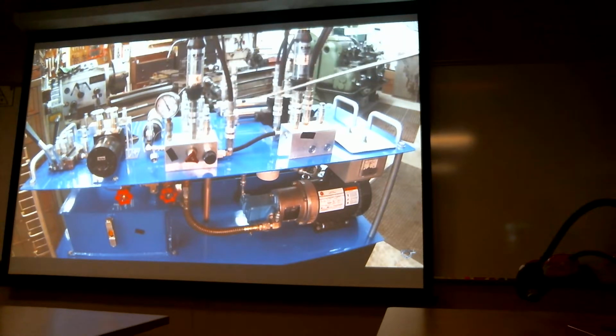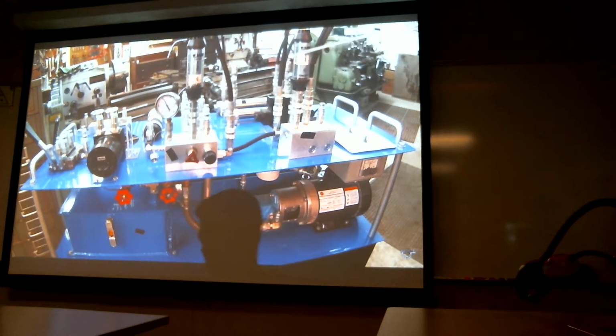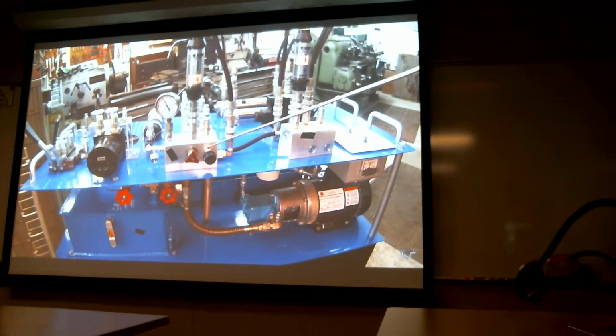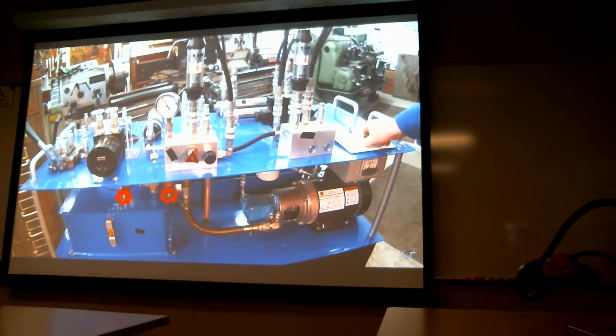I'm not doing any work, but the pump is still pumping fluid. All right, where is that fluid going? Okay, it's going over this relief valve right here and going back into the tank, through this filter back here. All right, so the only way you see fluid right here is when I actually actuate this cylinder and make the cylinder go in and out.